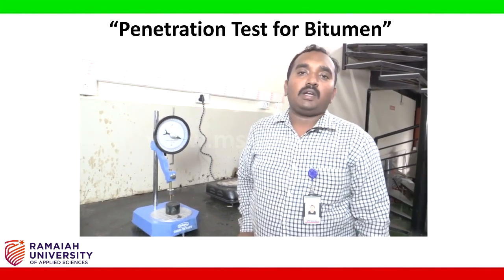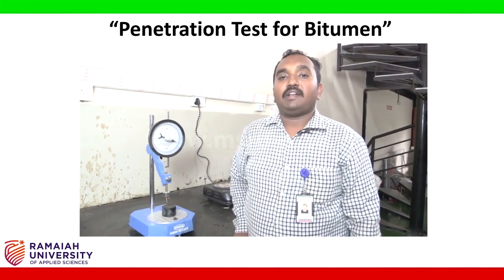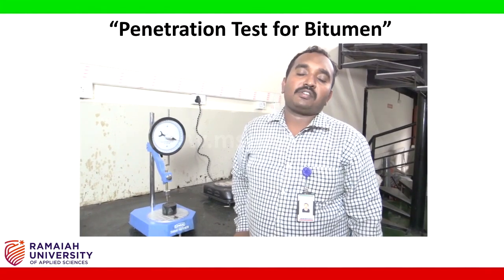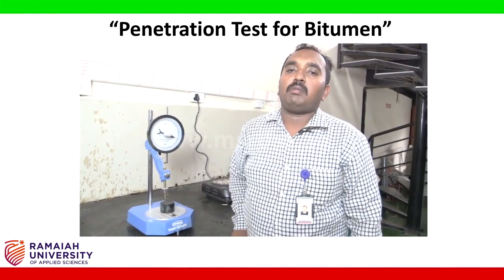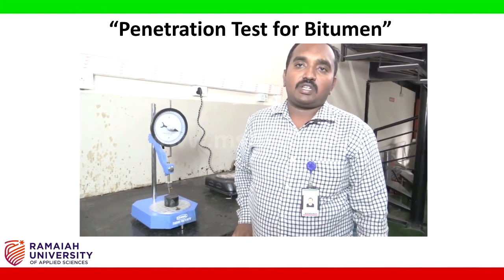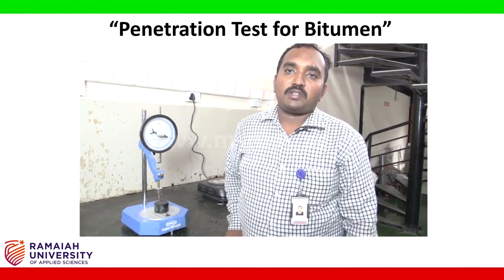For hotter climates, it's preferable to use the 30/40 grade bitumen, that is hard bitumen. For cooler climates or cold regions, we are going to use the 80/100 grade bitumen. This completes your penetration test experiment.